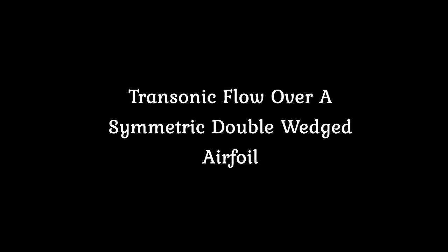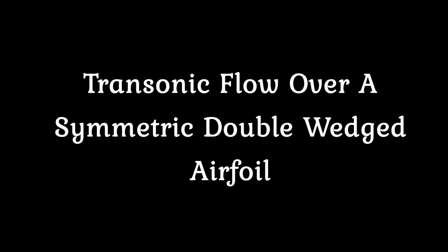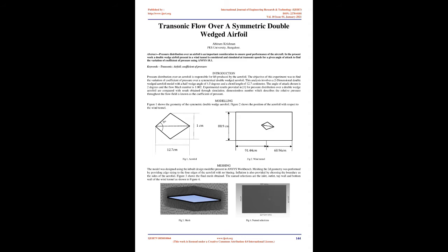Transonic flow over a symmetric double wedged airfoil. Abstract: pressure distribution over an airfoil is an important consideration to ensure good performance of the aircraft. In the present work, a double wedge airfoil present in a wind tunnel is considered and simulated at transonic speeds for a given angle of attack to find the variation of coefficient of pressure using ANSYS 18.1.